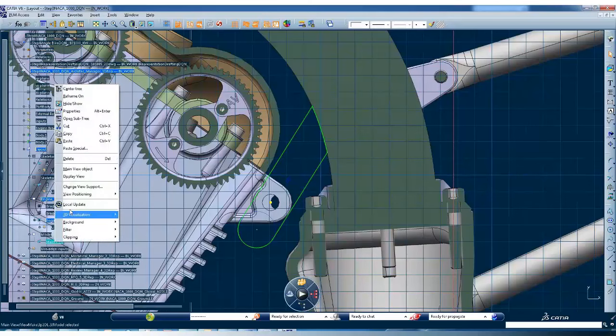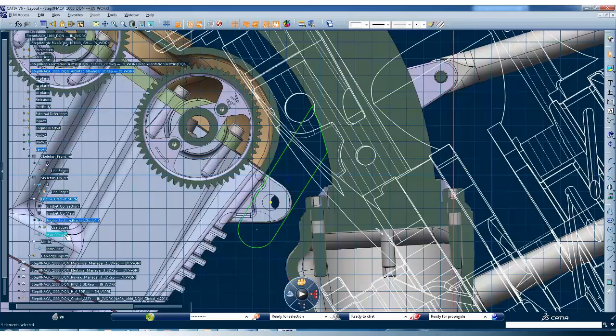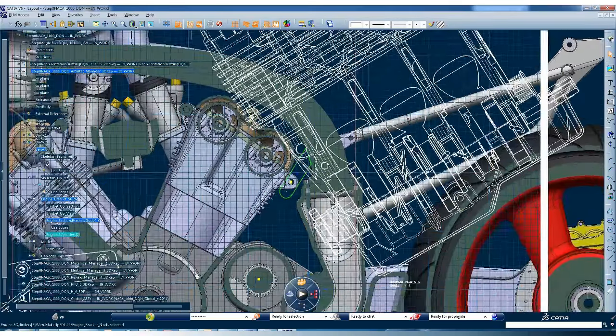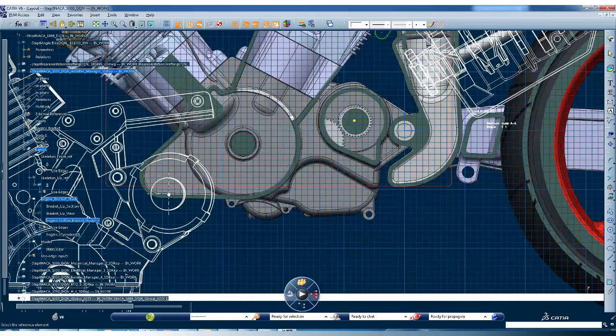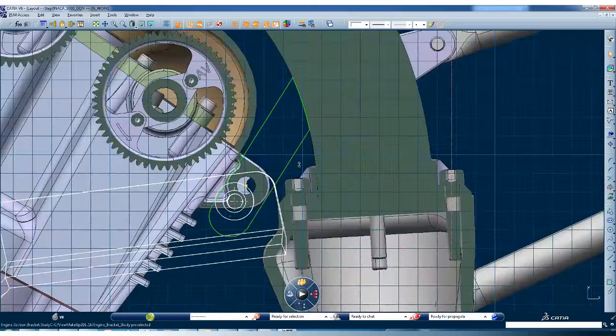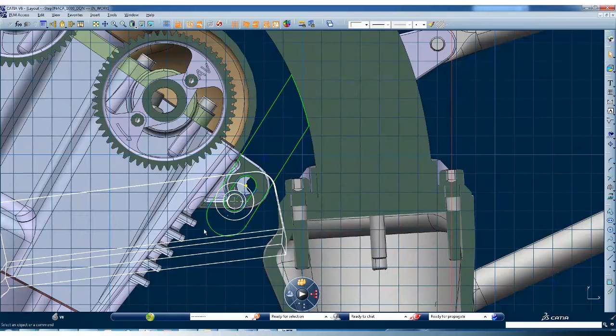The designer knows that in perhaps 1 year from now, he will have to deliver a new engine, which might perhaps have 3 cylinders. But this engine does not exist in 3D, only in 2D. So here we have imported a DXF format. You can see that he can very quickly decide to design a slot in the bracket which can accommodate both the existing 3D two-cylinder engine and the forthcoming three-cylinder engine modelled in 2D.